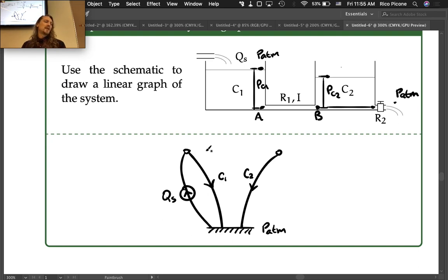But pretty much our signs are arbitrary. We just have to go back and interpret them based on what direction we drew them. Just like in a free body diagram, if you drew the force arrow to the right, then when you get a negative number, you know it was actually going to the left, right? So similarly with these arrows, we put them on arbitrarily and then we can adjust. Okay,